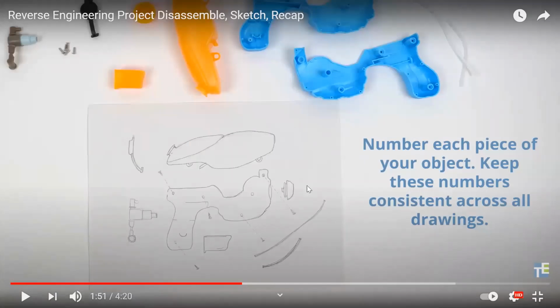You have to number the components. Suppose you have 14 parts or 15 parts or 10 parts, you number them 1, 2, 3. 1 stands for brake, 2 stands for suspension, 3 stands for seat, 4 stands for frame, then battery, controller. You have to name them, and give a number basically. When you give a number, you can write in the drawing, in a note at the side, 1 stands for brake, 2 stands for suspension. And you need to have the same numbers consistently across all the drawings.